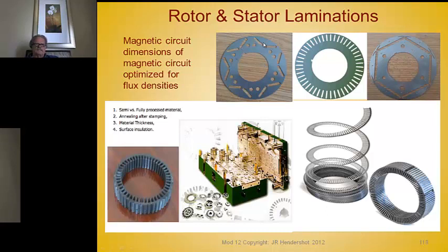And this is an IPM also, but here you have a slab magnet that goes that way with almost no reluctance component of torque. There's no soft salient pole in between the magnets. And in this example, they wanted to put this soft iron in between the magnets to give this thing saliency, to get a reluctance torque component. So to get the same magnet area, you make the magnet in two pieces and put it in a V, and that's what that looks like.